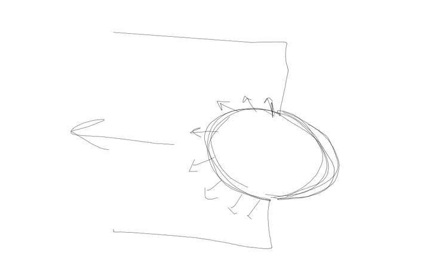So there's obviously a normal stress because these forces are all acting perpendicular to that semicircular arc. So how do you calculate that stress? Well, the hard way to do it is, you know that you've got a bunch of forces. What you can do is integrate the forces over that whole surface, that half a cylinder of surface, and you get the total force that's pushing against that semi-cylindrical surface.